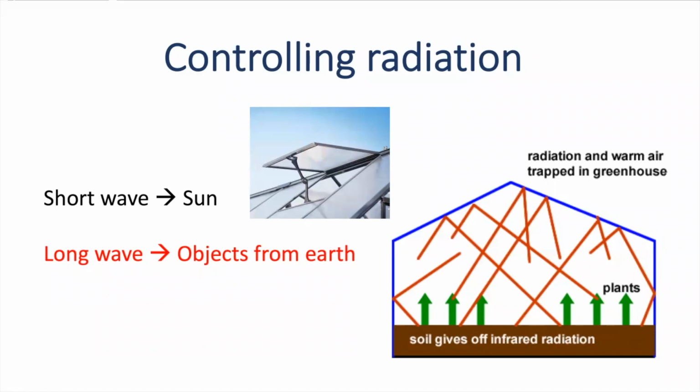Long-wave radiation is the heat emitted by particles charged from the ground. Depending on greenhouse covering material, we can keep long-wave radiation inside of the system. Plastic and glass usually help to maintain long-wave radiation inside of the greenhouse and promote high temperature. This is why when your greenhouse is totally closed due to the covering material, we must have a cooling system to consume heat inside. Otherwise, the greenhouse temperature will tend to go up all the time.